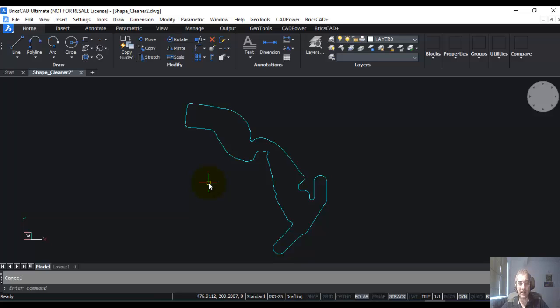The reason why we end up with bad data is because there are a lot of machine algorithms today which take 3D data and create the 2D profiles. Now, while that does a reasonably good job, it is never accurate. There are mistakes like duplicates or badly connected edges and so on. Now, for machining and other CAM operations, you need a clean, closed polyline, and creating that requires that you join all of them with a lot of precision and with painstaking effort. GeoTools and CADPower help you to make it easier for you.